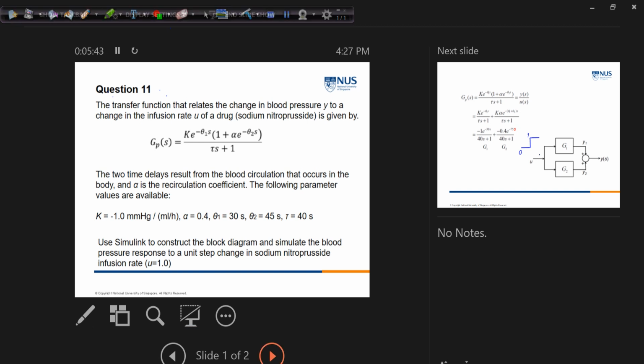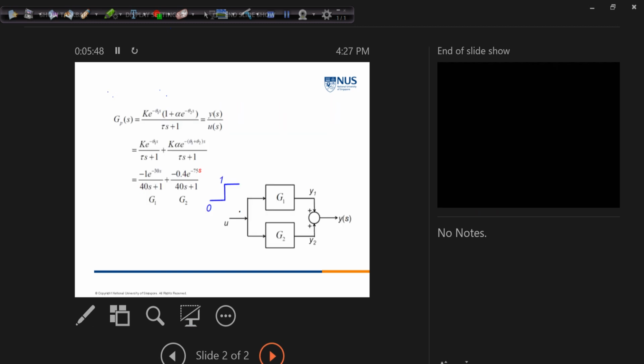If we don't directly write the G(s) into Simulink, it may be quite complex, with all the terms grouped together. So one way is to decouple it into several standard formats, which we can find the corresponding functions for in the software, and then use blocks to put them together to describe the process.